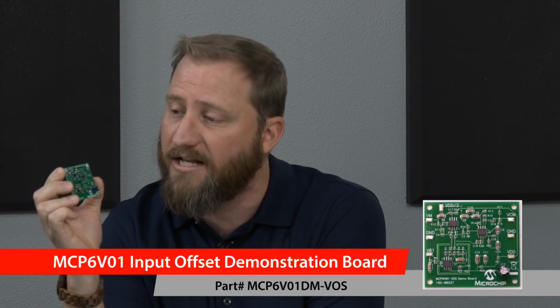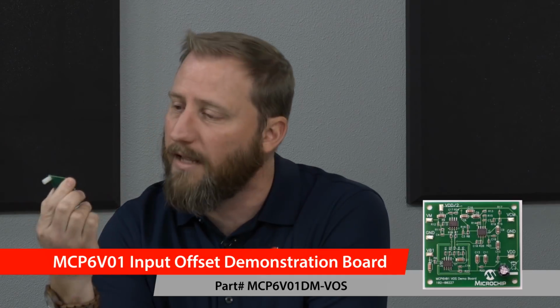So you can change the supply voltage, you can change the common mode input level, and see what happens if you step, say, the input common mode level. How does the amplifier respond to that? Of course, you can also vary, say, temperature across the board if you like, but this is a very easy board in order to really get the full experience of what these amplifiers can do and how they react to changing environmental conditions.